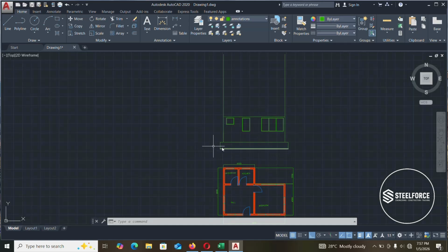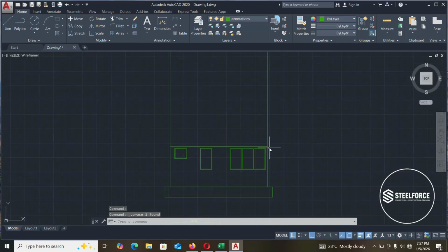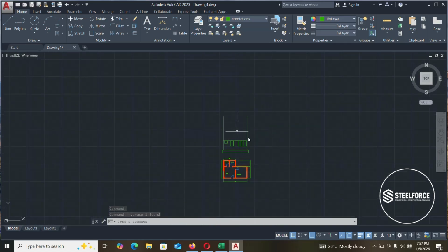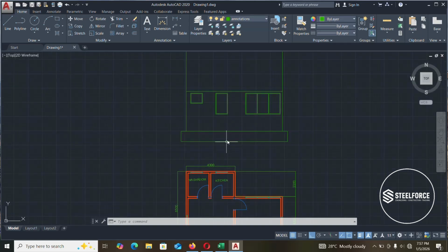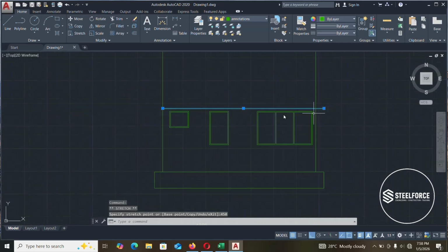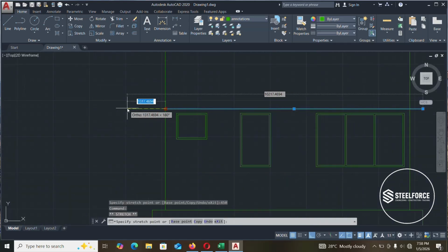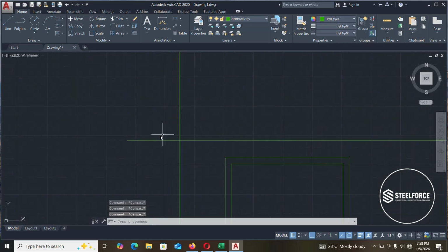So now you are done with the foundation, the floor level. Now you are going to add a roof. So when you stand here, what you see from here will be the fascia board and the roofing itself. So you are going to stretch this by another 450. Okay, the fascia, 450. Then we'll do the same here, 450. And we'll give the fascia board a height of 150 or 300.